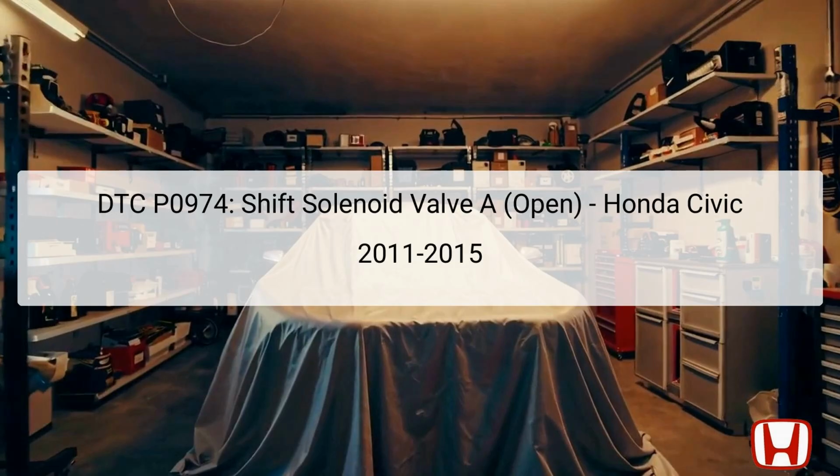Begin by recording freeze data and onboard snapshots with the Honda Diagnostic System, HDS, as this information will provide valuable insight into the vehicle's state at the time the DTC was recorded. This step lays the groundwork for a systematic and thorough diagnostic process.